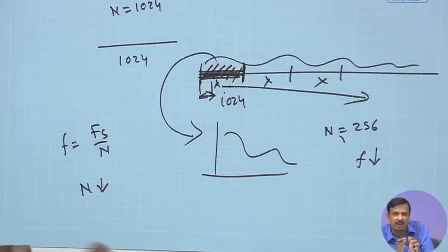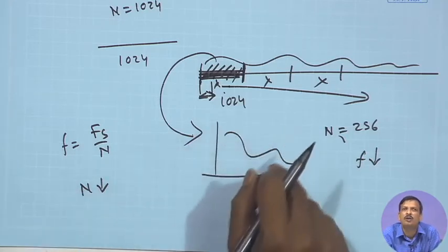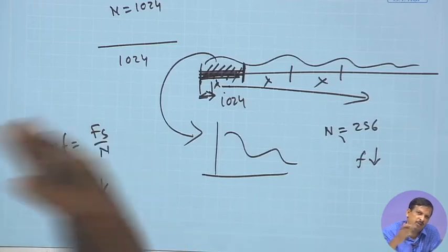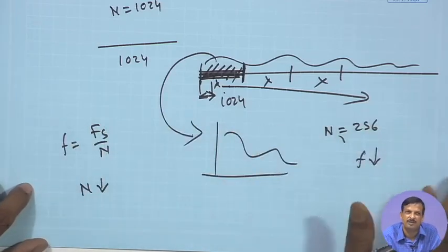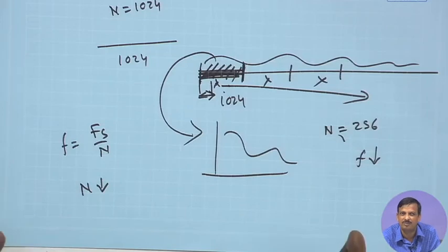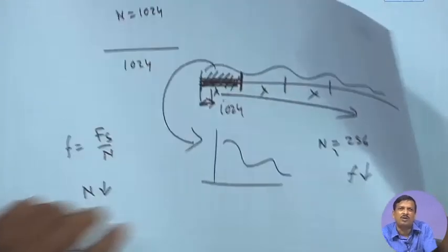If I take a long signal, time domain resolution is lost. If I take a small signal, frequency resolution is lost. So, this is the limitation of the Fourier transform. That is why people use other transforms like wavelet, EMD, and all kinds of things. Okay, so let us forget about those things.